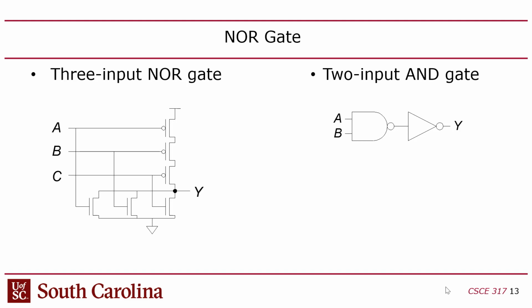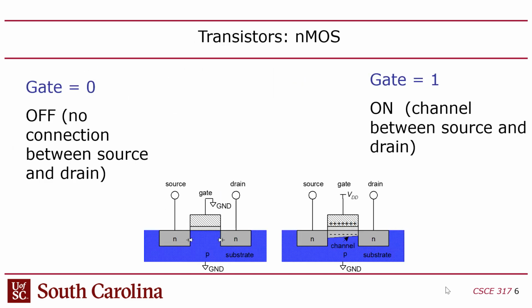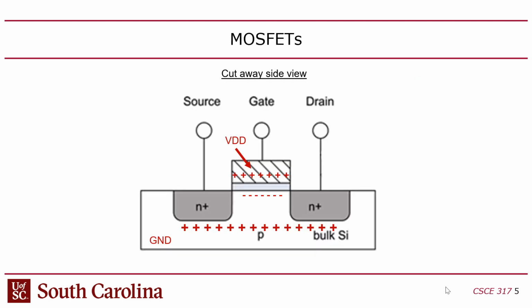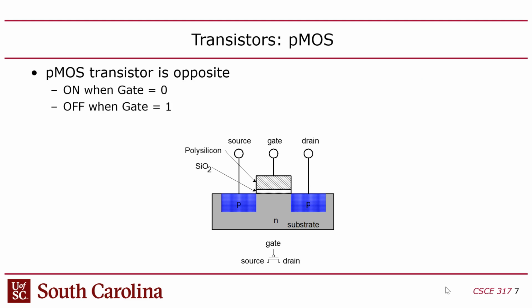So what's happening here is that when you set the input to this guy to 0, what you're really doing is creating a negative voltage, right? Because you're measuring the gate versus the source. Well, the source is at VDD. So if the gate is at 0 and the source is at VDD, you're putting negative VDD into this, right? But that's the way the PMOS actually works. It's the negative. Do I have a picture of the PMOS? I don't have a picture of the PMOS. Yeah, I do, right here.